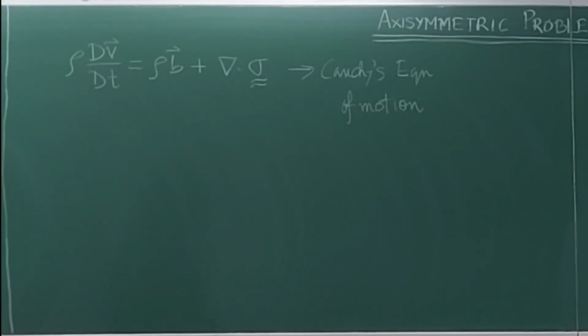We are not going to study all that. I'm just telling you for general knowledge. You should not be completing a course on solid mechanics and not have heard of the Navier-Lamé equations. As written, this is the most general version. It has the time dependence, and the dependence on the body force per unit volume. This body force can be due to gravity. It could be a body force due to electromagnetic sources also. These are the two most common types of body forces, but we are not going to deal with any of those things.